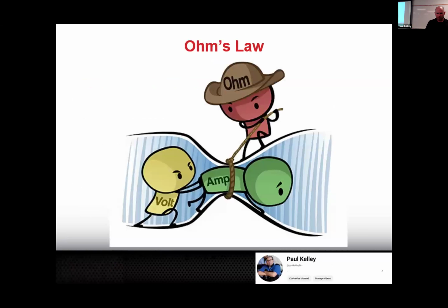Here's the visual again. You've seen this, right? Sometimes, honestly, if you really want to cheat on your ASE exam, get this tattooed on your forearm. They can't really get you in trouble for that. The people at the test center won't even know what that is, but you'd be like, oh, well, the ohms doubled, so that means we're pulling up on 2 ropes now. That means your amps are going to be halved, right?